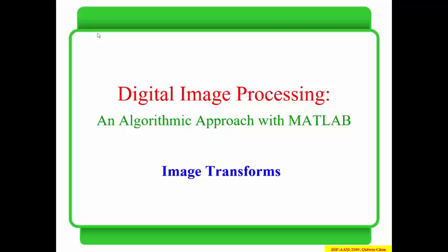You didn't try it? Okay. So I will give you a small hint here. With respect to the old versions of MATLAB, MATLAB was installed together with the camera drivers. For the time being, this is not the case now. MATLAB is to be installed first. Then after that, on demand, you can select an add-on that corresponds to the camera hardware and you can install it.